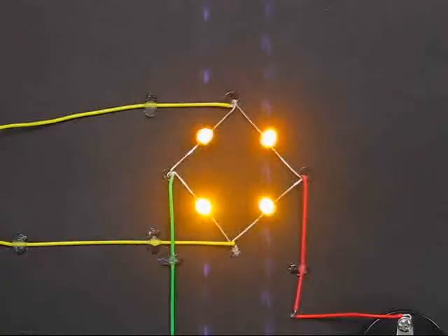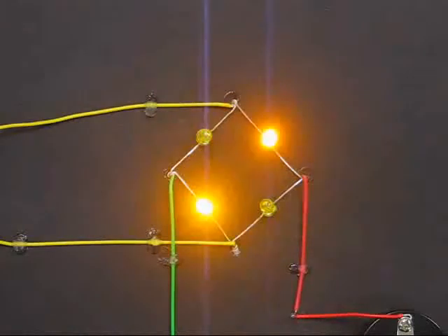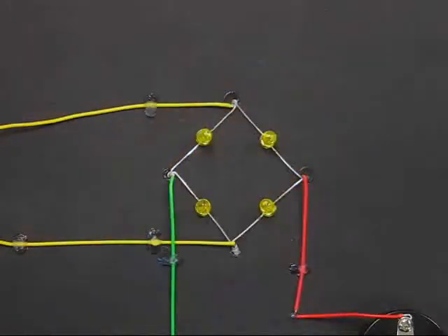The diodes of the rectifier bridge are turning on and off in pairs on opposite sides of the diamond. Here, this is regular 60 Hz AC, and you can't see the blinking with your naked eye. However, if I use a signal generator to provide AC to the bridge with a different frequency, you can actually see what's happening. Here is 6 Hz, and here is 0.6 Hz.